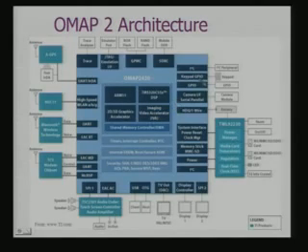In fact, there is a keypad GPIO, general purpose IO, to interface a keypad, a camera serial parallel interface, that same parallel serial interface that I had talked about earlier. It has got again a security block, that is, if I want to use some kind of an encryption service, so for that hardware has also been provided. And you have got the UART, and here we are showing a modem chipset.